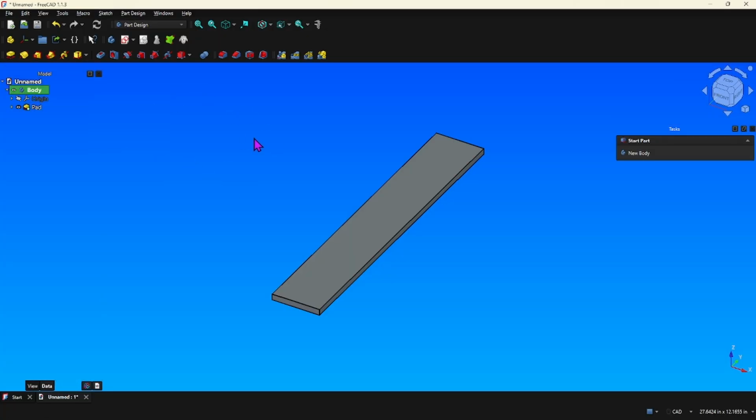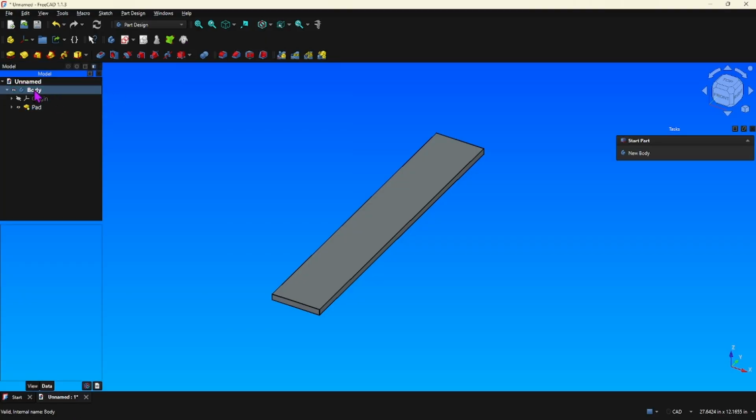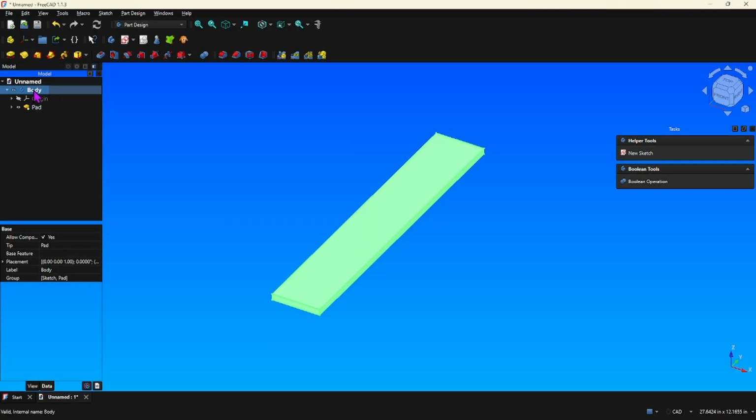What I'm going to do is show you the clone command up here. What you do is you select a body. When you select this body, you can copy it, like with a Control-C, or you can go up here and edit and copy it. And when you make a copy of it, it stands on its own. It's not referenced back to that body.